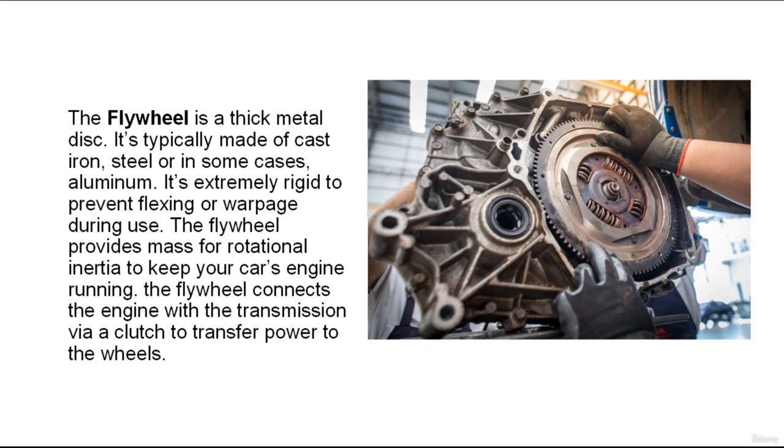A heavy flywheel is only found on engines equipped with a manual transmission. Engines with automatic transmissions have a flex plate and a torque converter. The weight and motion of the fluid inside the torque converter serve as a flywheel.